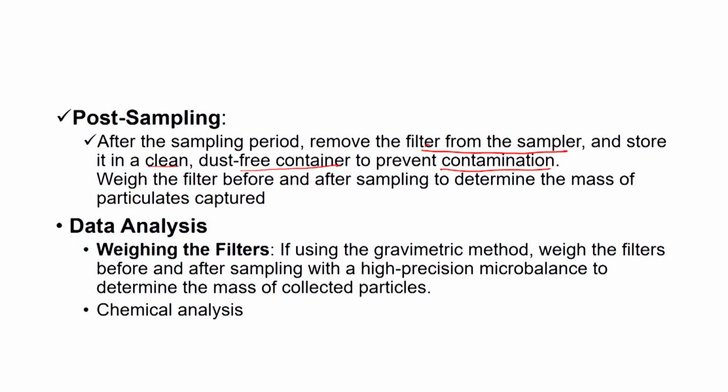Usually after sampling, you have to pack your filters, because some of the volatile organic compounds might be lost, and if they are lost, then there will be a problem. We prefer to pack them in a Ziploc bag. But sometimes volatile organic compounds are still lost. Usually the filter is wrapped in aluminum foil.